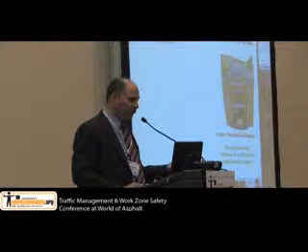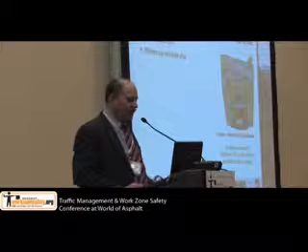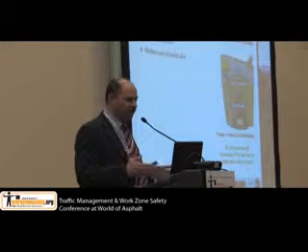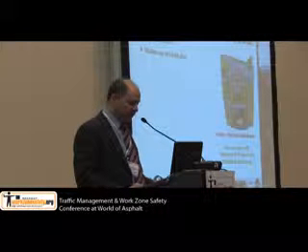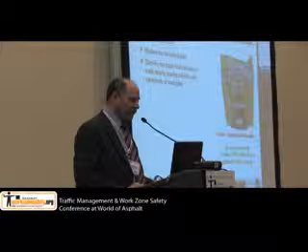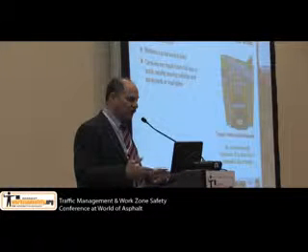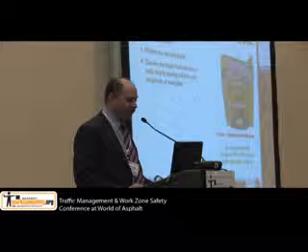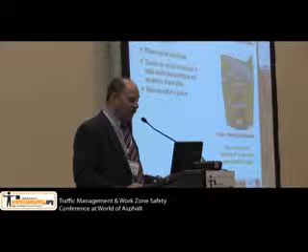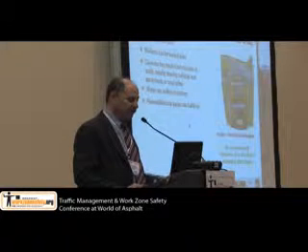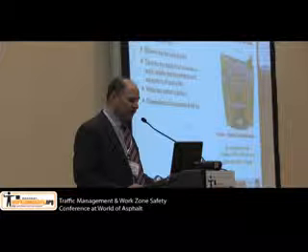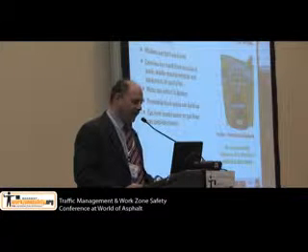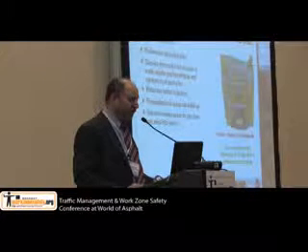First we have to really define what a trench is. It's an excavation that's deeper than it is wide and that workers can be buried alive. Cave-ins can result from stresses in the walls, nearby moving vehicles or equipment, or a spoils pile. Water can collect in the bottom. You can have toxic gases or flammable gases in the bottom. Gas can come from a nearby sewer or gas line.